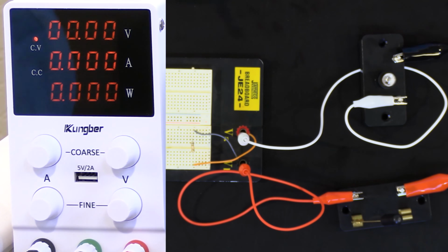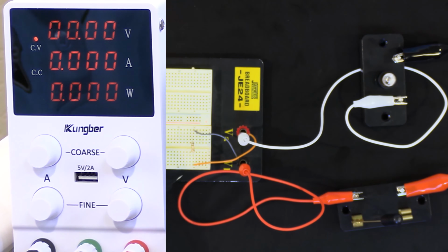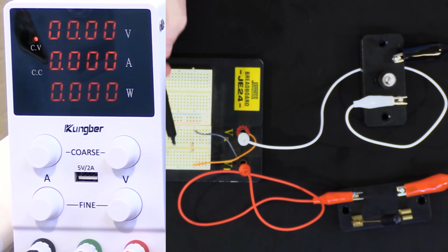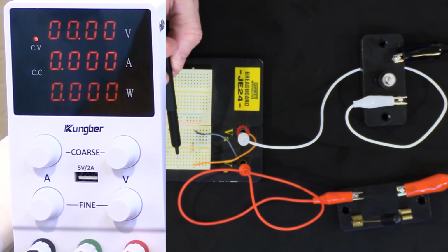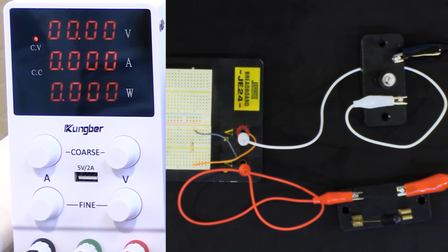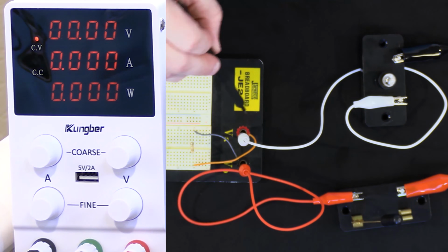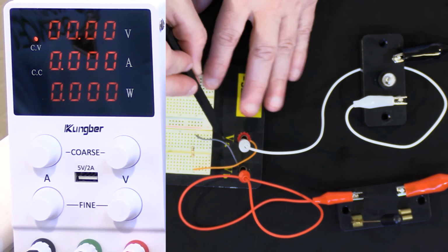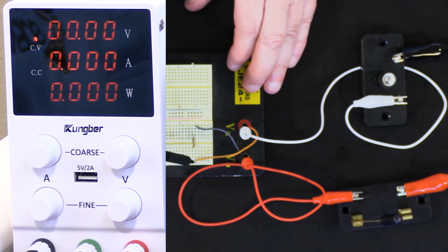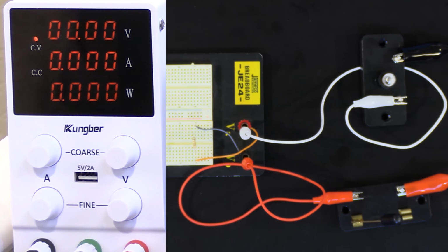The way this breadboard works here is the resistor is plugged into this line here. When you see this line of little holes, all of these holes are physically connected together underneath. There's a wire coming from this terminal up here, and there's a gray wire going and plugged in here, and the resistor is plugged in the same row. So anytime you plug something into any one of these dots, they're all physically connected underneath.